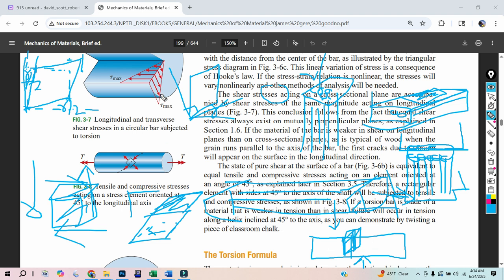So yeah, if our square bolt is actually this 2x4 and we're trying to make this diamond shape, cool. Like the soda straws of a 2x4 are actually, I don't know, well, let's say they're kind of challenging to shear through, you know. Yeah, enough said. But if this top layer is going that way and the bottom layer is going that way, these soda straws are really easy. Again, we talked about they're easy to slide past one another.